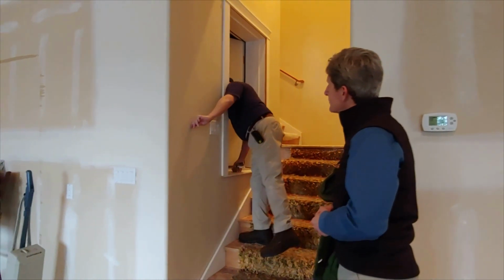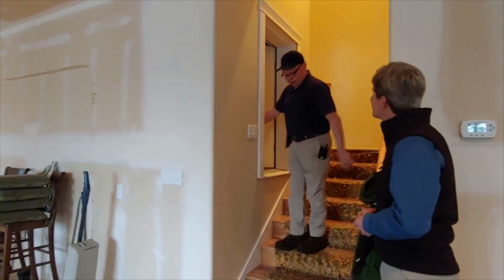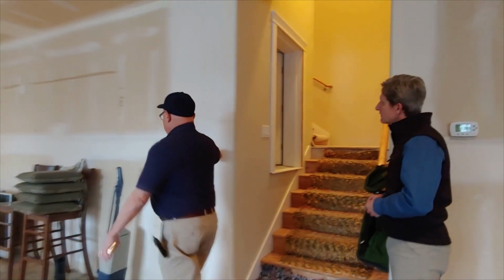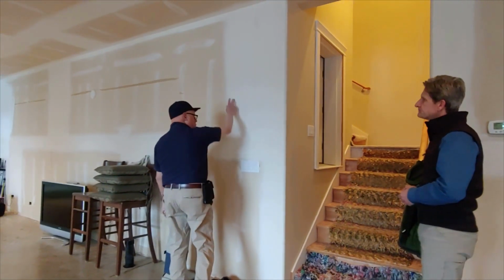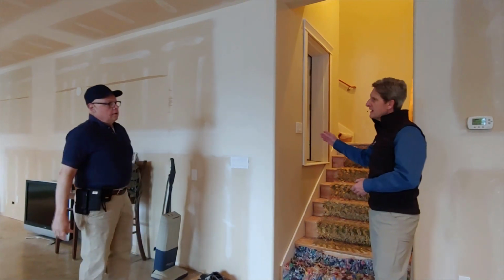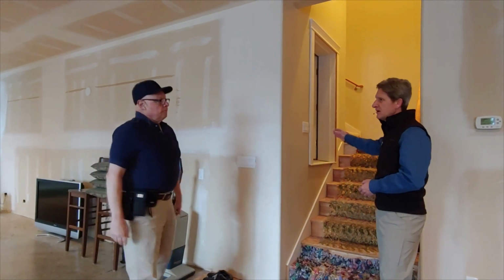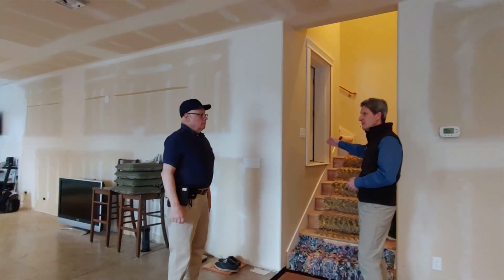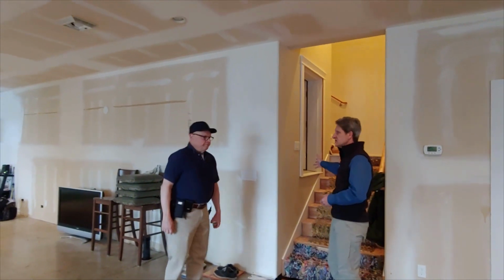And I might look in here and I can see some concrete in here. So I know that this particular wall stops right about here, concrete below, sheetrock above. This is probably furred out. So when you're measuring your wall thickness and you have an unknown like that, you just simply take the tape measure and do the math on the difference of the wall. That's right. And that's a quick way to do it.